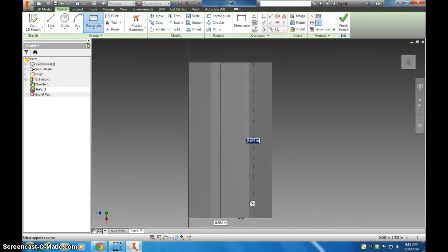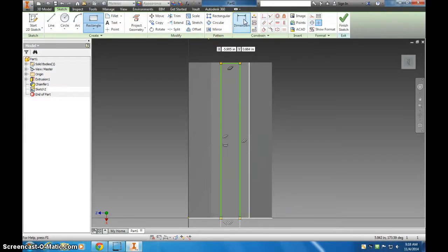And if I want, before I click to set this in place, I'm not clicking yet, I'm just going to hit Tab, and it moves me right to that bottom data field, and that's 0.625. Then I don't have to go through and dimension it. Dimensioning it would work just fine.